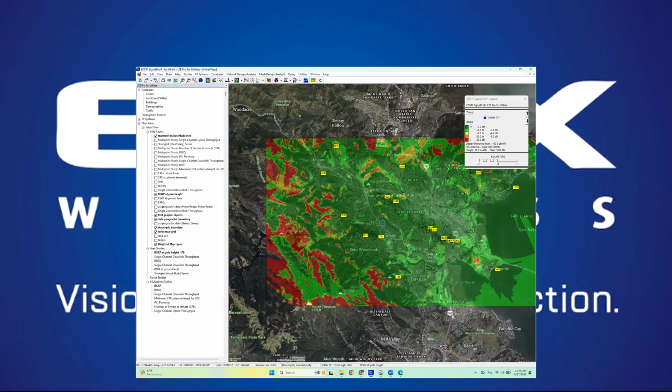It says if you're using the DAS module, can you still run a query study for the same percentages by dB level thresholds? Yeah, great question. Absolutely. By the same token, you'll establish your study grid around the building with whatever grid resolution, and then you'll want to set a polygon for your area of interest and carve out the areas that are actually in the building and maybe are actually occupied areas.